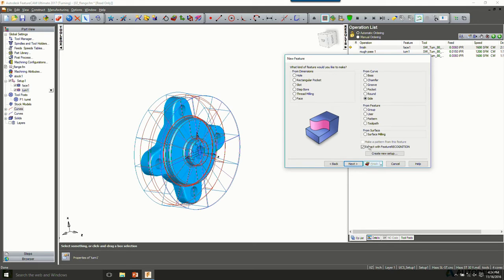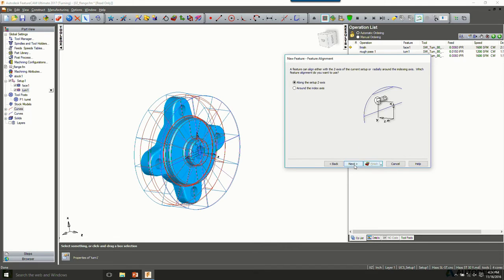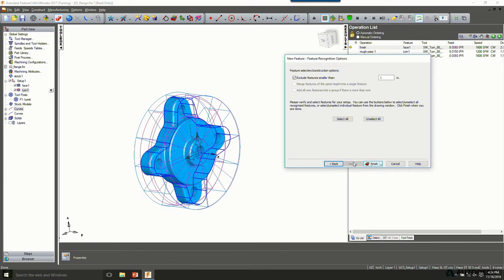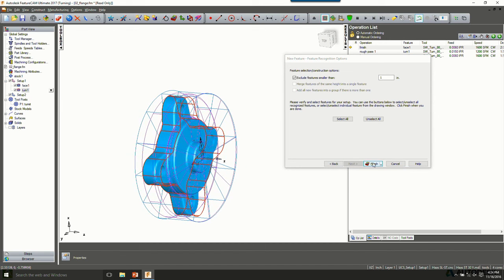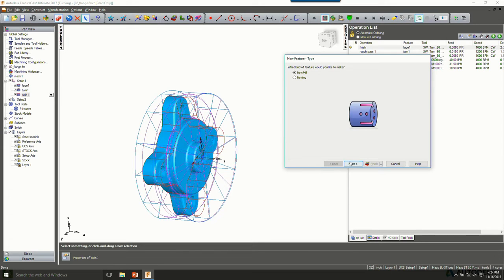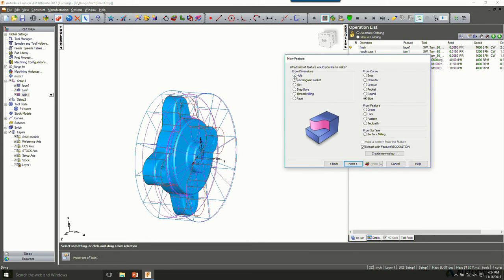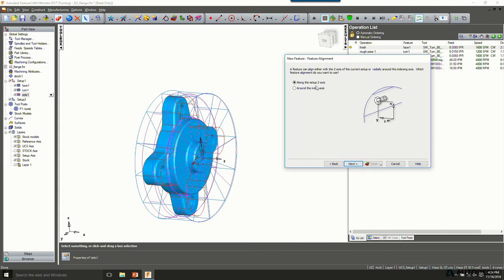I'm going to find a side feature. I'm going to extract this with feature recognition. And I'll just choose automatic. Finds that side there. If I'm happy with that, I select that, say finish. Okay, the last part are the holes. So I'm going to go create my holes.